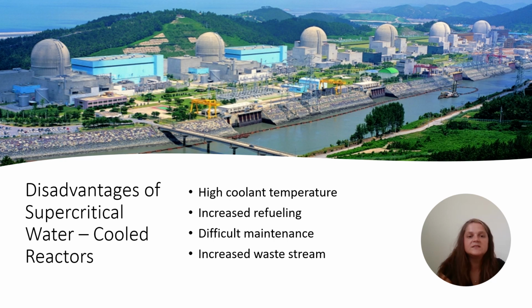The single-phase steam flow transport of radioactive materials from the core to the high-power turbine can hamper maintenance and inspection of the turbine and increase radioactivity dosage to staff. The last thing with the supercritical water-cooled reactor is the fuel assemblies contain more parasitic materials than those existing reactors. So this increases waste stream.